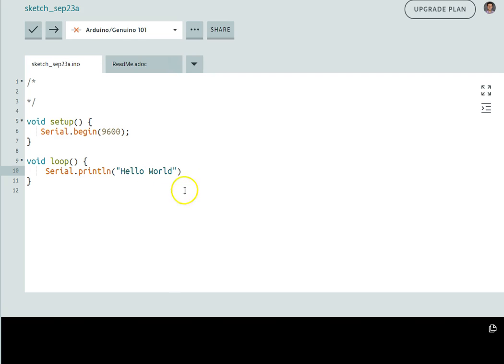And then maybe I want to call it hello world. Right? So basically what we're doing is we're just telling the Arduino, in this case for the serial communication, to set the baud rate to 9600, and we can set that to different baud rates as well. 9600 is usually just a standard. Then our void loop, and it's printing the line. In this case, if I want to ever write out full text, this is just in general for coding, you always put it in between quotation marks. So print line, hello world. And then what it would do is it would print the line, hello world.